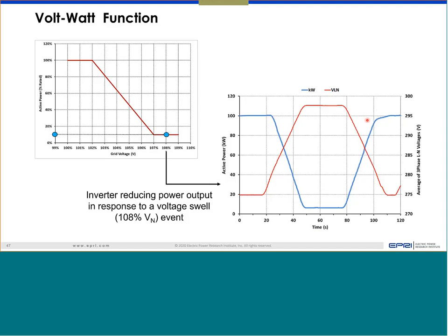So you should configure it at somewhere like 105, 106: okay, now even if I tried, the voltage is still going high, and at that point I'm trying to reduce the power. That will, of course, impact the revenue, but what is the alternative? If I don't do anything, voltage may go to 110% and shut down. So what you are offering the customer, rather than abruptly shutting down, is trying to reduce the power to keep the voltage low so that you don't have to go to the shutdown phase.